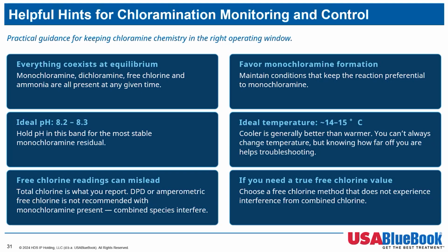Second, the window. pH around 8.2 to 8.3. Water cooler rather than warmer. You often can't change temperature, but knowing how far off you are tells you how hard the chemistry is working against you.